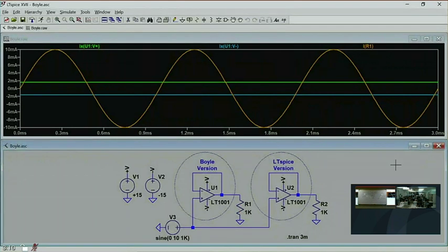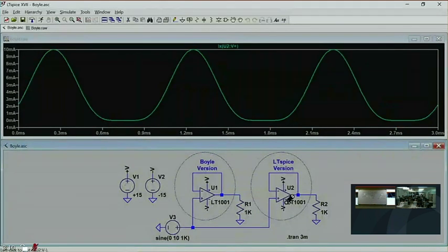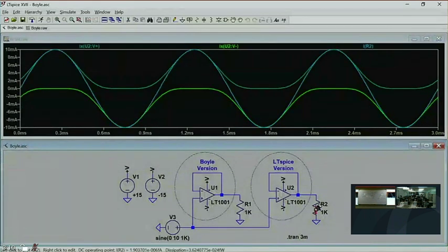Because if you try an LT Spice op-amp model, positive supply pin current, negative supply pin current, it's just going to steer current above the pins. It's boring. You know it's going to have the right small signal response, the right drive capability response. We do as best we can on the output impedance, so we overshoot into a capacitive load will be about right. We'll model the input capacitance as normal mode and common mode. So if you use the high impedance feedback network, the extra pole to the input capacitance, that'll all be modeled both modes. Input common mode range, it just works like the op-amp. It's actually boring. Okay, so that's the deal.